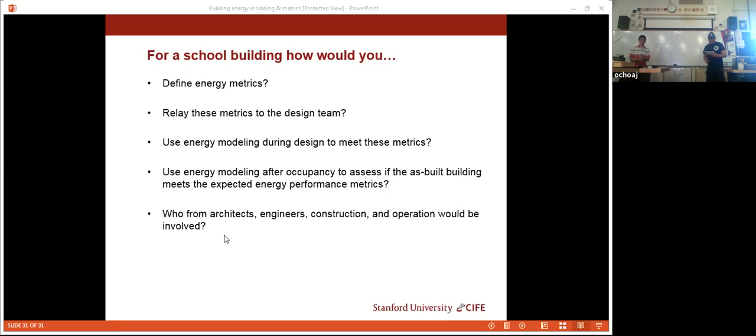So to obtain overall performance of the school building, we found a way to actually detail that. First, you take how many kilowatt hours of electricity from the PG&E bills, and graph it over a year span, right? On this graph, it looks like kind of a bell curve because during 6 months, which is during summer, you will use more energy to cool your building. That's sort of the hot summer. That's what it looks like.